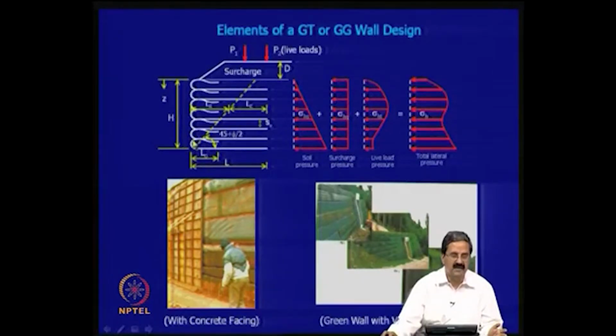But then you can't leave just the soil like that. So, you need to have some sort of erosion resistance, some length of this geotextile coming like this. That is what we have to provide, some sort of length, maybe 1 meter, 1.5 meters. You take a geotextile, put it like this, like this. Everywhere it is like that, and this length can hold it on, so that thing is avoided.